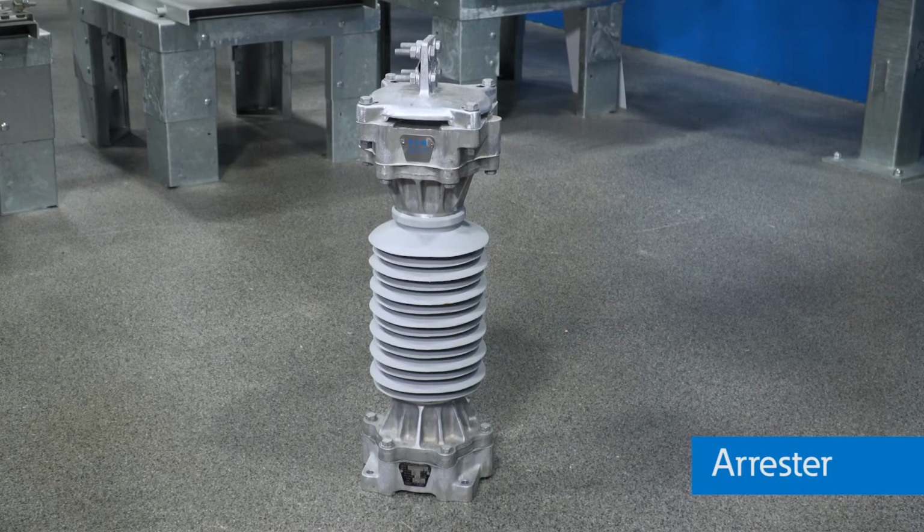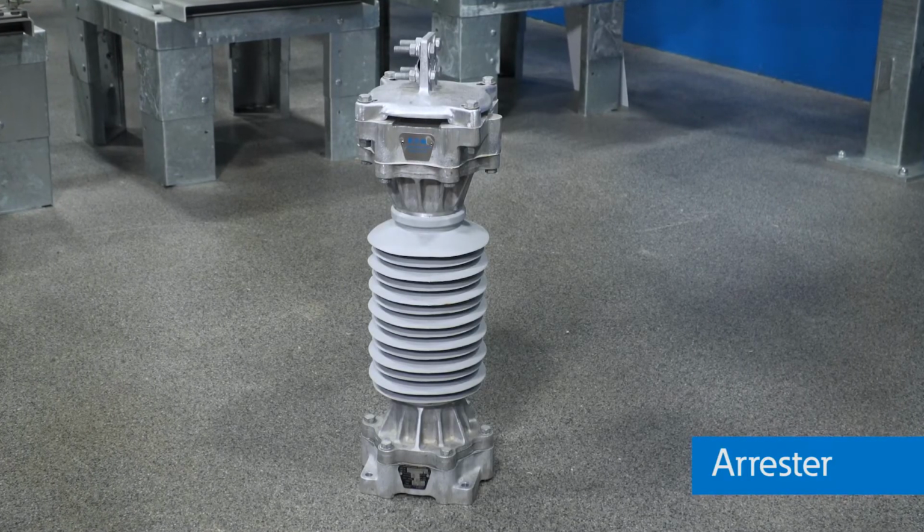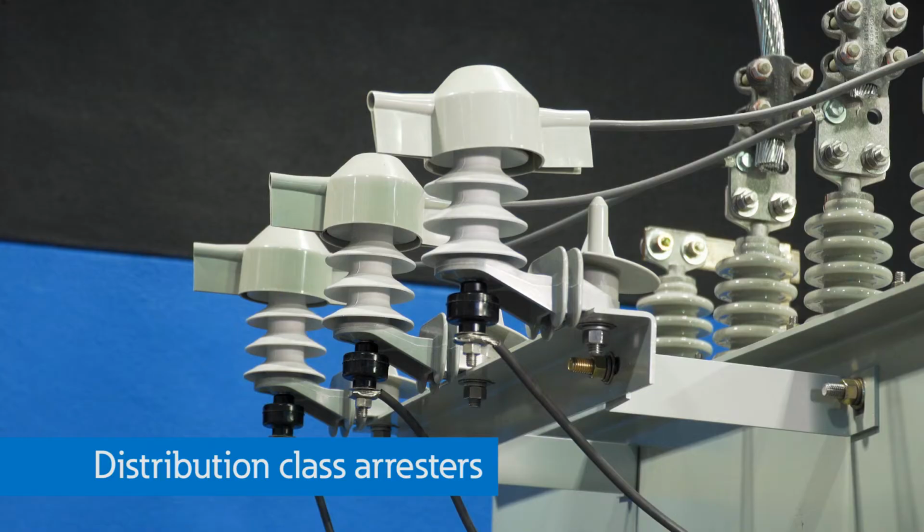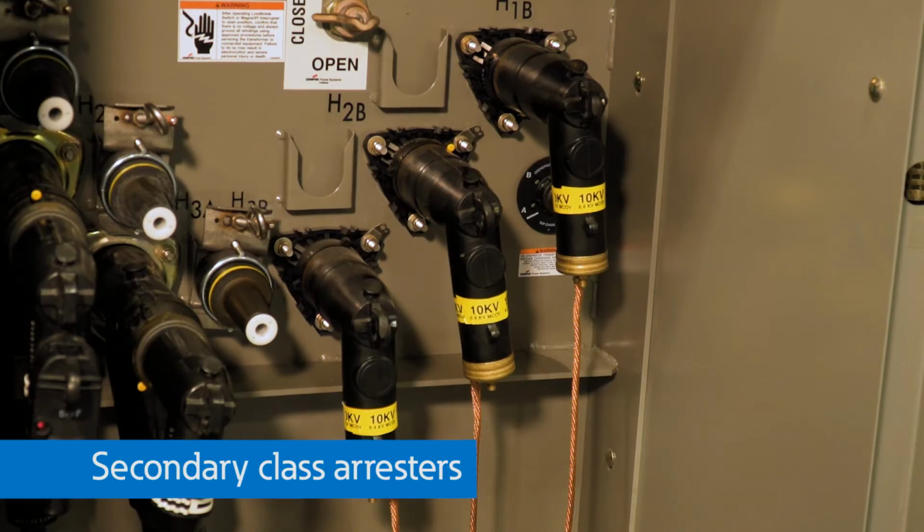The most common type of overvoltage protection for a transformer is an arrestor. Arrestors protect from overvoltage events such as lightning, switching surges, and ferroresonance by reducing the surge voltage seen by the equipment. There are 4 basic arrestor classifications recognized by ANSI, which include station, intermediate, distribution, and secondary arrestor classes.